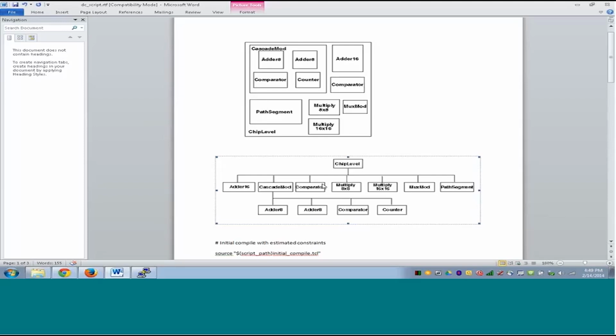So that's why first pass synthesis is necessary. One pass is necessary at least to give DC the timing data. If there is no synthesis done, DC will not have any timing data and it cannot characterize. So before characterize, one pass compile is needed.